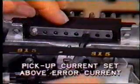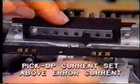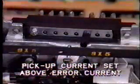The pickup current should be set so that it's above the estimated error current generated by the CTs for the through fault. This system is quite economical and is often used on low voltage buses. But you can see that it's slow and not very precise. More sophisticated arrangements are needed for protection of high voltage buses.